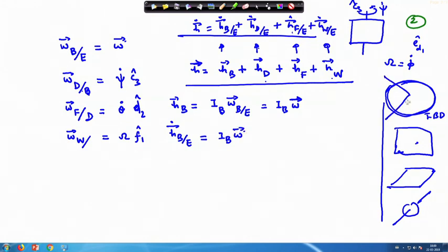There is a frame fixed into this, which we write as E 1, E 2 and E 3. This is your body frame attached to the main body, this B. In this body frame, the moment of inertia of this main body is not going to change, and therefore we can write it like this, times omega cross I b times omega. I am not putting the dot here unnecessarily; I am considering that this part will give you a vector and this is multiplied by a vector. So, it is very simple.